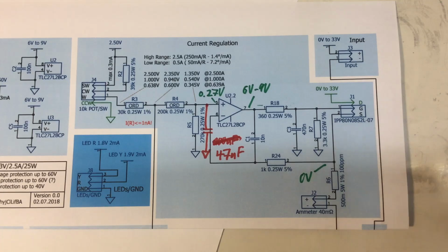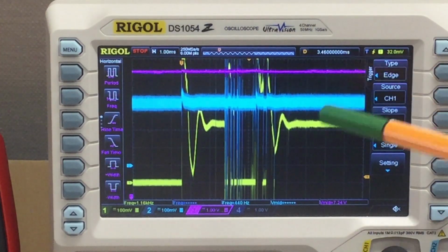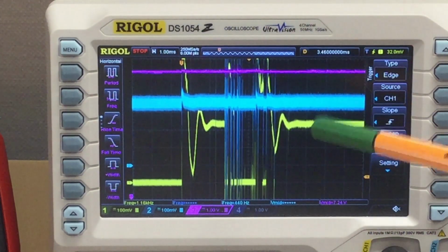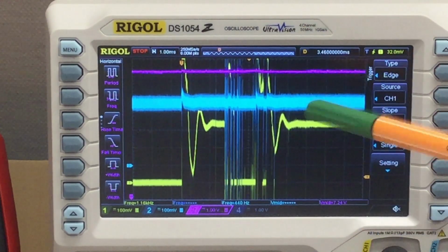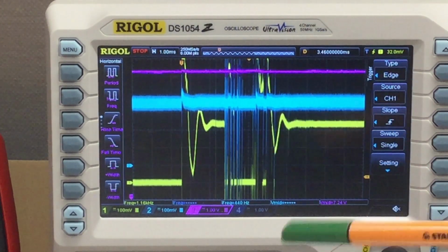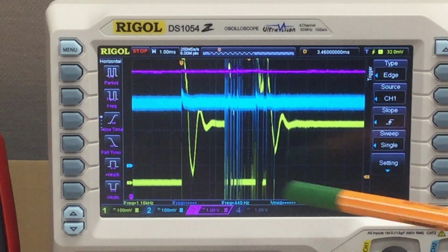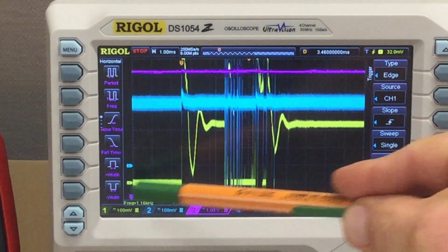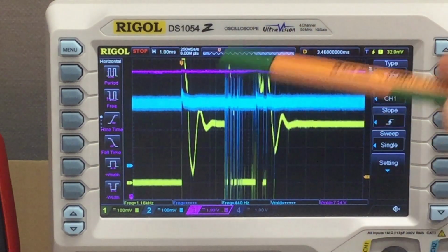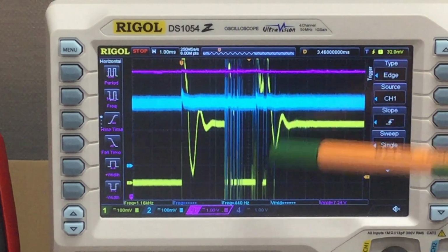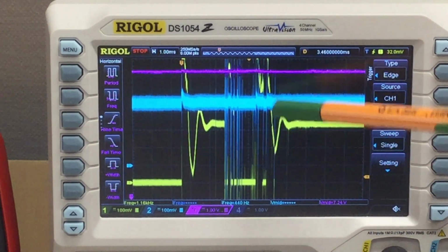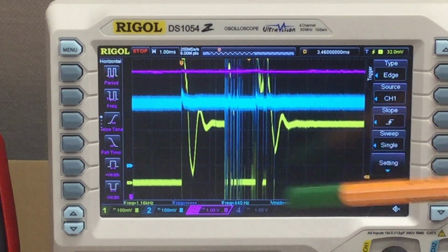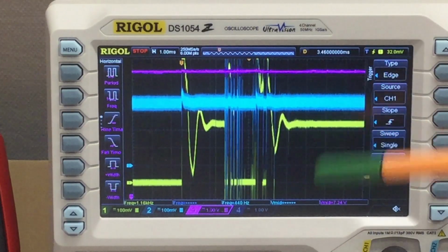Let me think about that. The resolution was actually quite simple, and it worked the first time, in the first iteration, which is a first for this project. I'll show you in a second, but you see here that violent bouncing of that big switch, and after the bouncing stops, within a millisecond the current is stable, which is what you want.